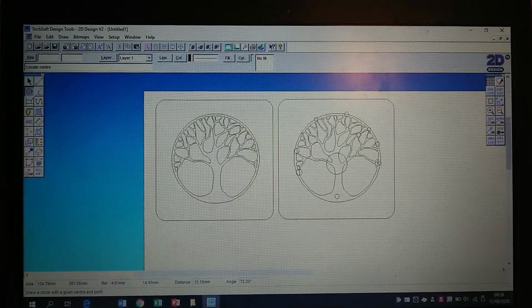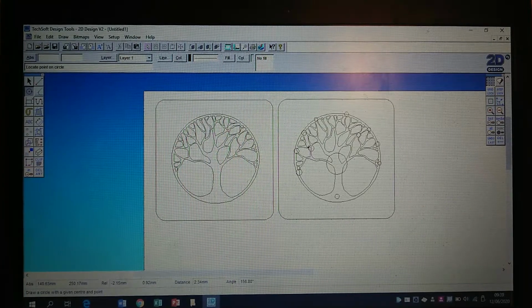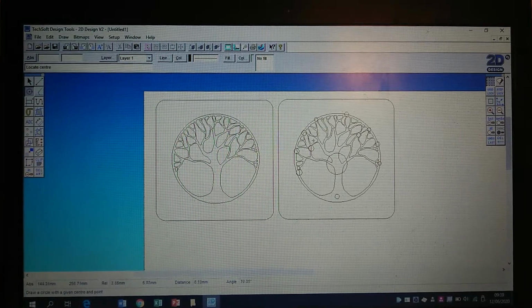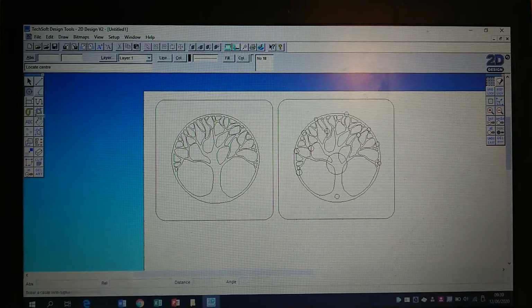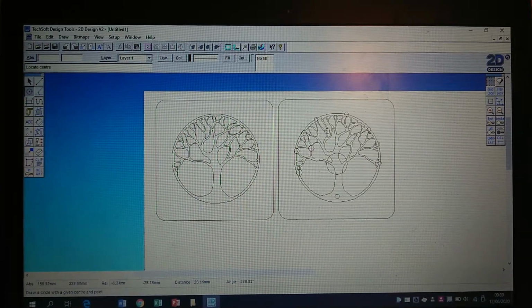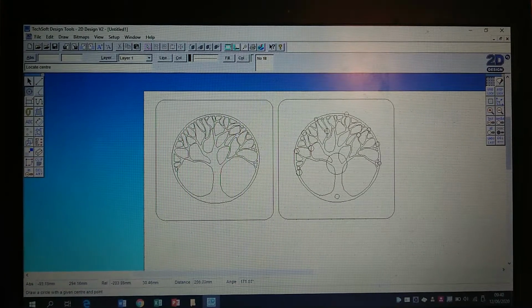There could obviously be a problem with this design. If I'm pewter casting this design, the big problem we're going to have is it's quite thin. The pewter might not run down here. That is always something to be aware of if you're pewter casting. If the pewter starts running down here, gets too cold and dries, it won't join up. So it's not the best choice, it might work. I think I can make this one work, but as a rule, I would pick thicker lines than this.